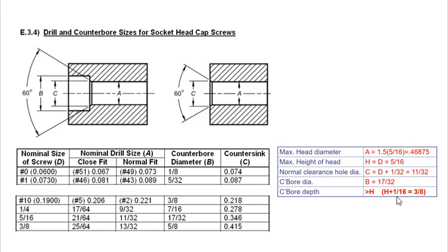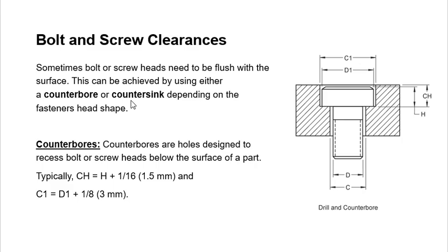This is how you calculate your counterbore depth, remember, which is going to be greater than your head height, h. So you add 1/16 to it. This one is not from the table.